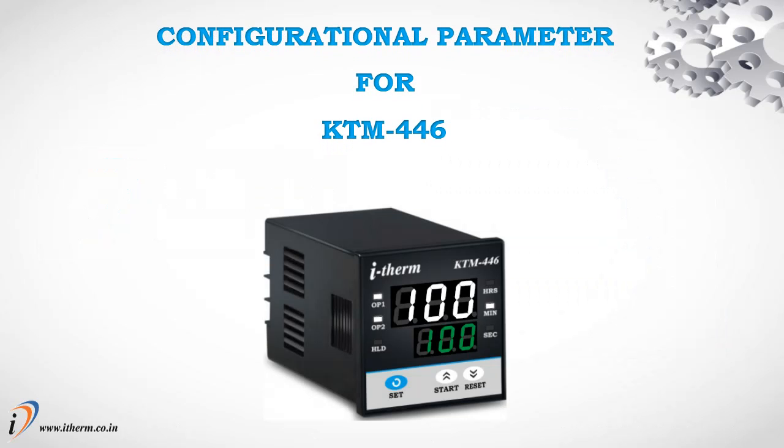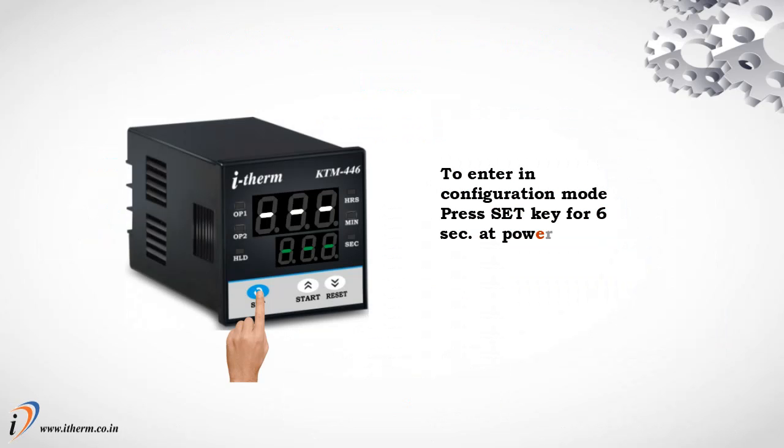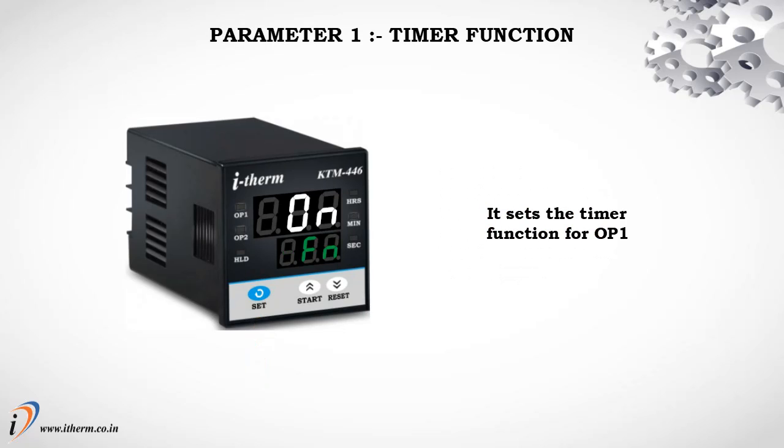Configuration parameters for KTM 446. To enter configuration mode, press the Set key for 6 seconds. At power on, the version number will be displayed. Parameter 1. Timer function. It sets the timer function for output 1.